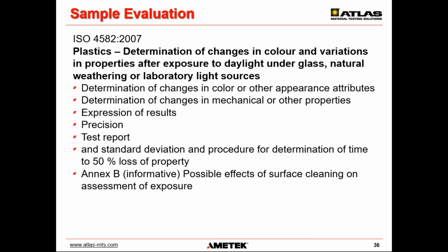And as I mentioned several slides ago, the plastics industry also gives guidance on sample evaluation. ISO 4582 instructs users on relevant evaluations for polymers after being exposed in a weathering or light fastness test. And it gives guidance on determination of changes in color and appearance attributes, determination of changes in mechanical properties, how to express the results, the required precision, how the test report is to look, and the required accuracy.